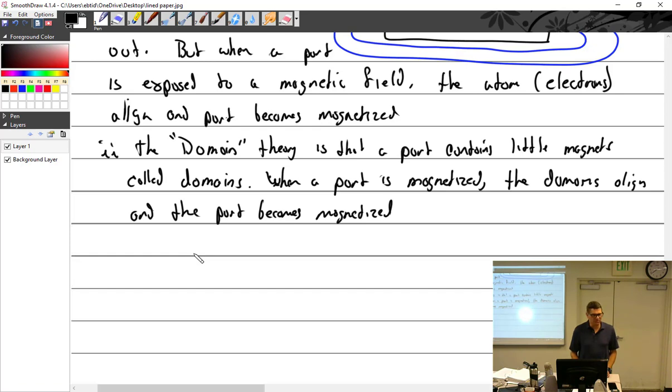Now, interestingly enough, what would happen if I used AC current? Nothing. You get high. Actually, AC current magnetizes quite well. It's very shocking, I know, but it has what's called a skin effect. When we use AC current to magnetize something, and I don't really understand why it does this, the magnetism rises to the surface, and it causes magnetism to go across the surface instead of deep down inside of it. DC magnetism puts it way deep inside. Actually, it won't show as well on the outside as it will with AC. AC will give you a much better indicator if we use one of those little Gauss meters that you guys are using, which checks the magnetism. You would get a higher reading if we used AC because it's more on the outside than on the inside.